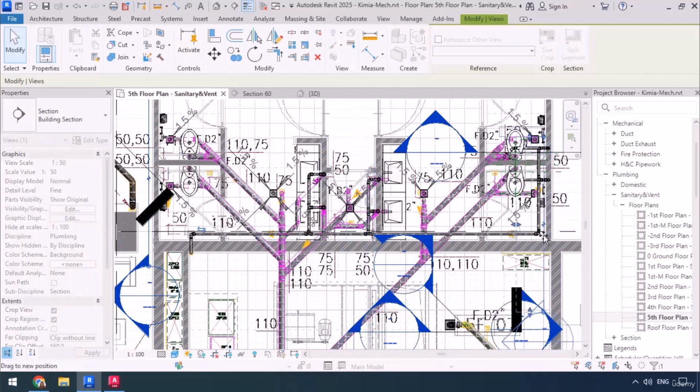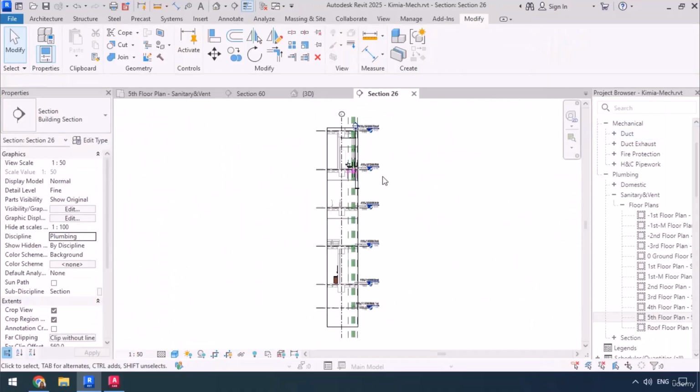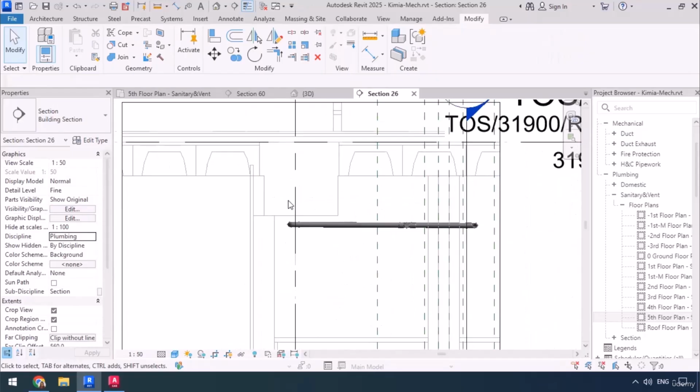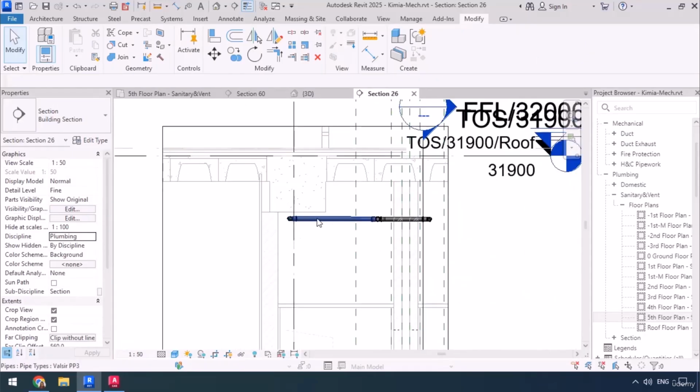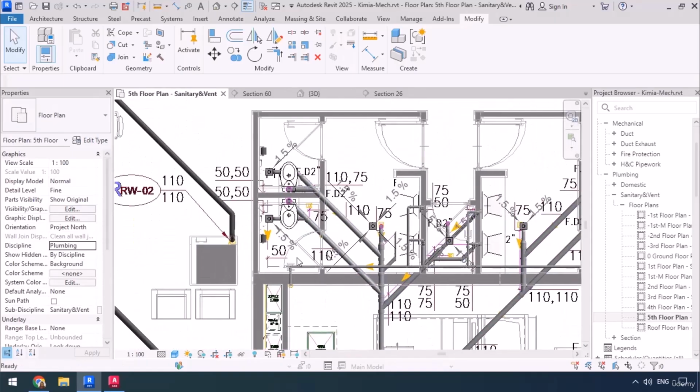On this pipe, right click and go to view. Now here it is. It's going below the beam, but you should always come back and check, and if you notice any interferences, then you're going to have to lower your pipe if possible. Or you could even reposition it from below the whole beam, because sometimes you might not be allowed to have supports below the beams. Remember that we're going to need some supports for this pipe.